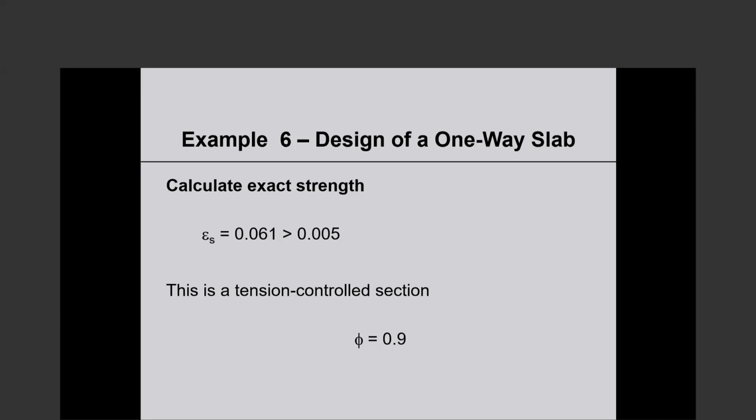And code does not prescribe any maximum strain in tension for tension control beams. Is there any best practice to follow? So what he's saying is epsilon sub t, from 0.005 onwards, it's all tension control. Is there an upper limit? Is there any good practice to follow? That's what he's saying.